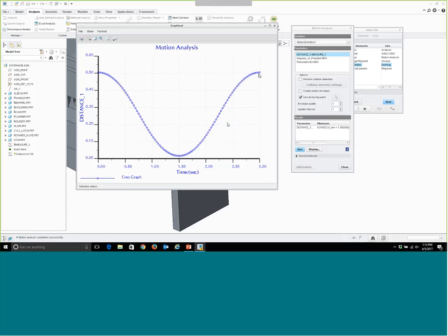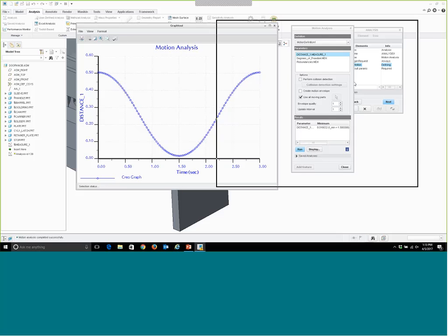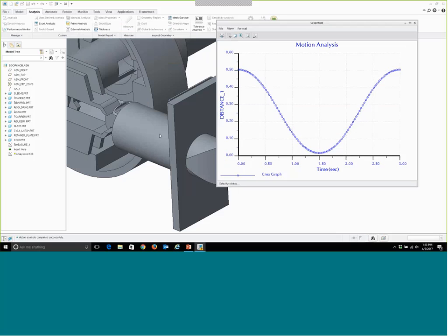So as we discussed previously, what is important for us is that the distance between the back of the cylinder and that stop component has to be at least 0.2, because when we put that spring in there that pushes the cylinder back out every time you release the handle, it does have a fixed length when it's compressed that we have to allow for.